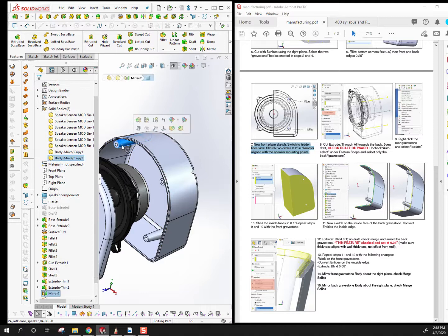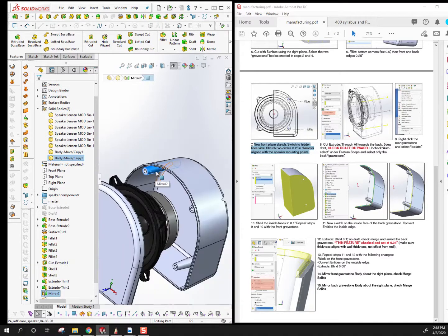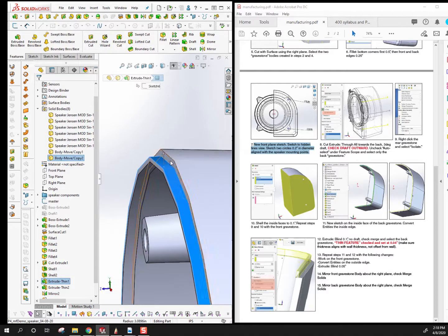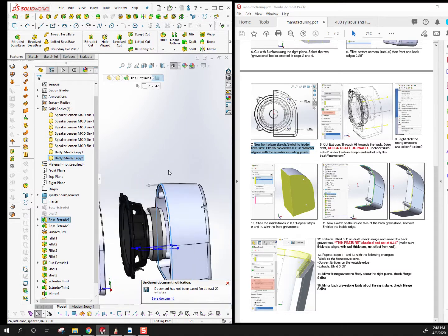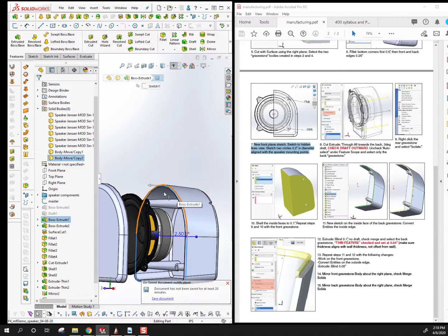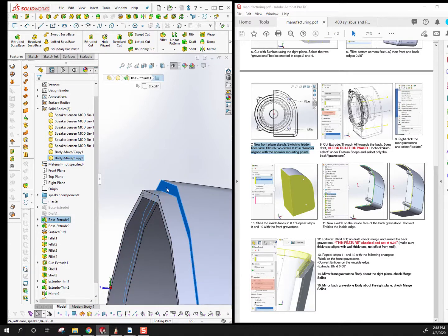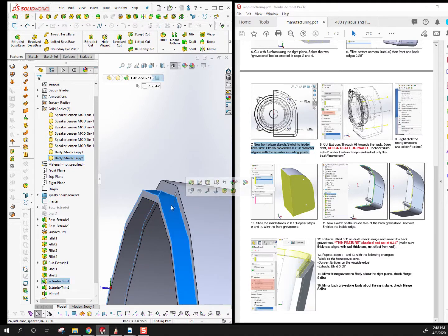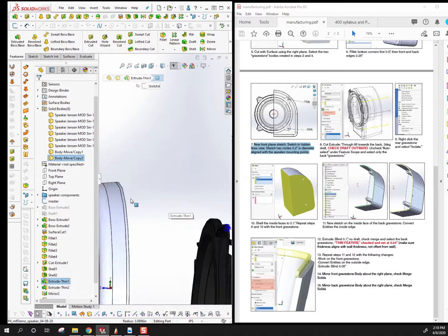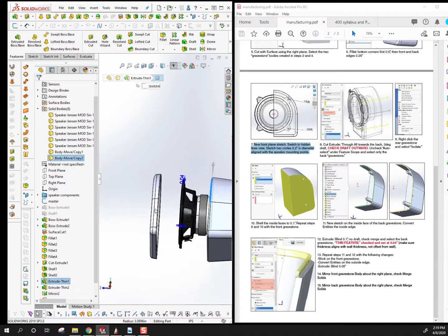Again, to be absolutely clear, for Project 4, bosses are not required. This level of detail of part line is only required on your final, or for homework if you would like to build this kind of part line into one of your existing concepts or ones that you're working on. I just ask that you cut a 0.1 inch gap between your front and back pieces. On one piece, extrude a thin wall to the inside that's taller. On the other piece, extrude a thin wall to the outside that's shorter. And that's basically required.